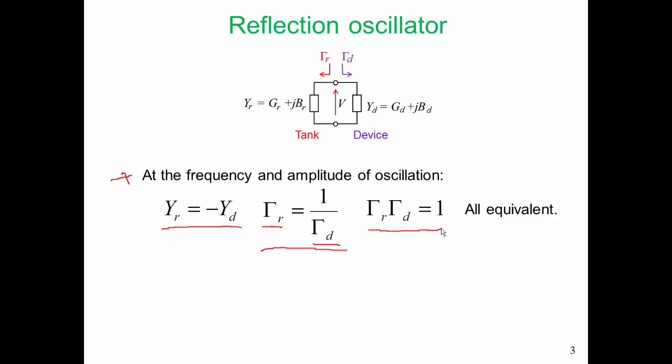But most of the time, our active devices really do look like transconductances, and so conductances are the normal way of looking at things. We can certainly take a transconductance and with some contortions and circuit design, we can make our transconductance element, which of course is the transistor, look like a transresistance. But it is much easier to look at this problem as a transconductance problem, or just a conductance problem.